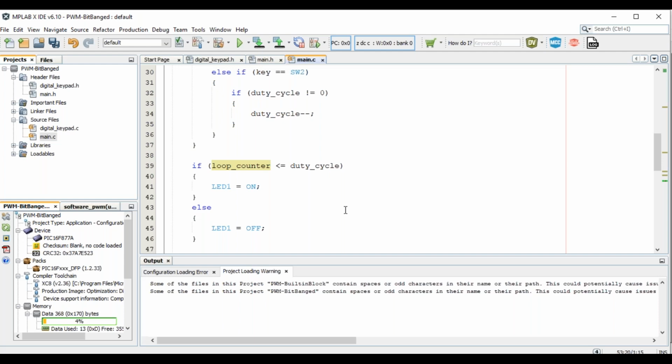In short, SSD. Now each segment of the SSD is going to have an individual LED provided to it, and in order to glow that particular LED of the segment, you have to provide either a 0 or a 1. Now that completely depends on whether you have a common anode configuration or a common cathode configuration. Now, in our case, we got to know what we have is a common cathode configuration. So you are going to have all the cathodes connected to ground in common via the transistor, which acts as a switch.